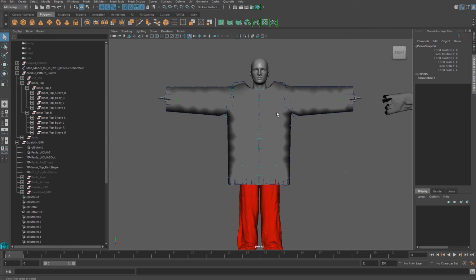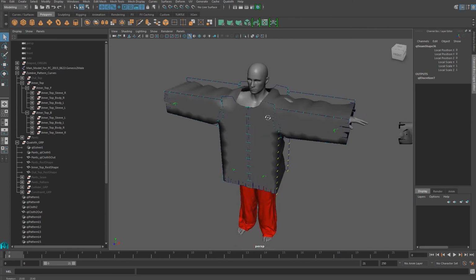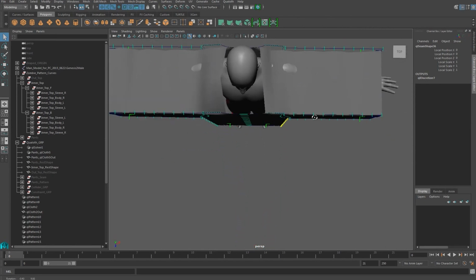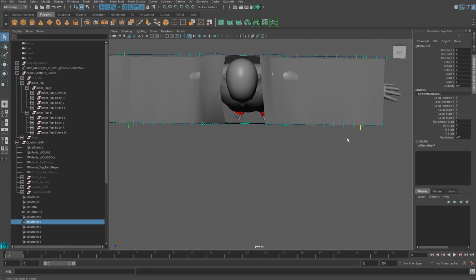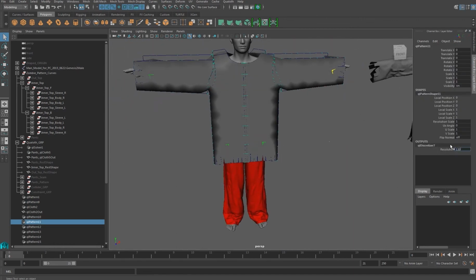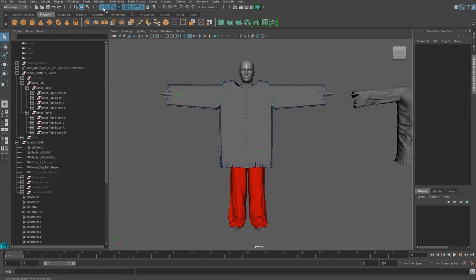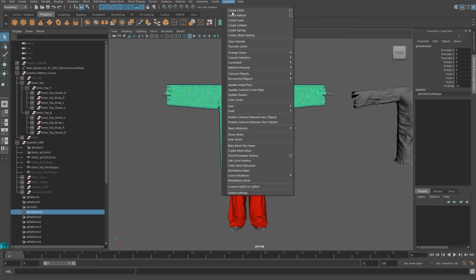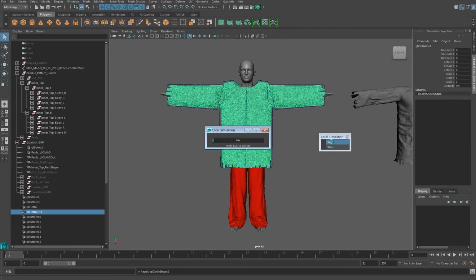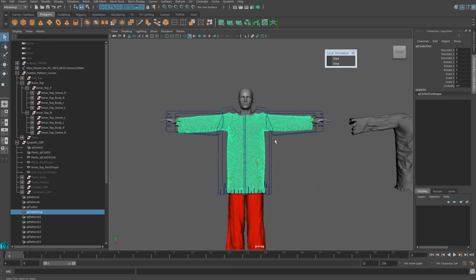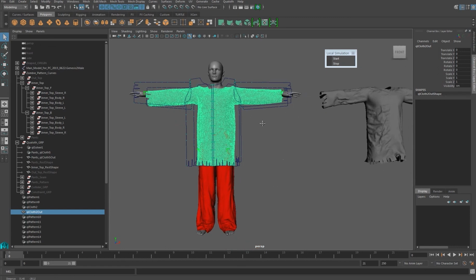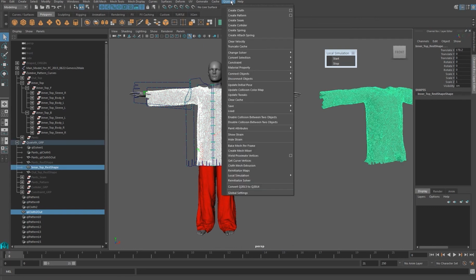When you're finished with simming, click on Pattern icon in the viewport, then raise Costume Mesh Resolution to 120 in the channel box. Select Costume Mesh and begin local simulation to put the cloth on the character. Select the top cloth and red shape mesh that we already have in order. Click on Connect Red Shape command to apply it to add details.